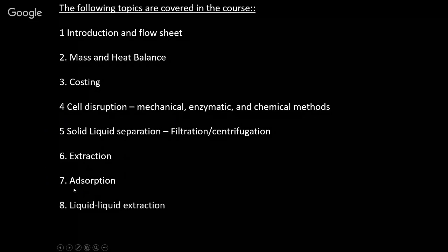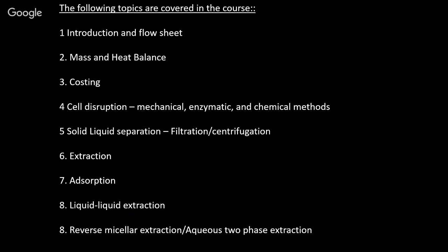Then came, of course, liquid extraction. The liquid extraction, like I said before, we looked quite a lot at the design equations, number of stages calculations, efficiency, how much solvent is required for extraction, and so on. And again, in the aqueous two-phase extraction, we looked at the concentrations of the desired product in the upper and lower phases, and what the partition coefficient is, and so on.